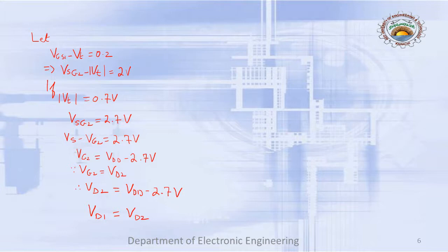If we use a diode connected transistor, what is it that we obtain? We are obtaining a gain which is equal to GM1 over GM2, and it is fairly independent of the bias point. It depends upon the device dimensions. If we use a diode connected transistor comprising an NMOS transistor, then the device size difference would be fairly large. If you use a PMOS transistor, the device dimension mismatch would be half of that.